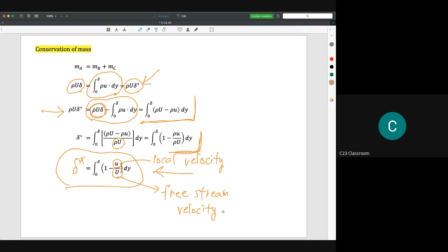Okay. So if we have a flat plate here, and this is the boundary layer, we have the velocity distribution, and the small u is actually the velocity of every molecule inside the velocity distribution. However, the capital U here is the free stream velocity, which is the velocity of fluid which is not yet in contact with the flat plate. And if you want to draw the velocity distribution above the boundary layer area, the velocity here is also equal to the free stream velocity.